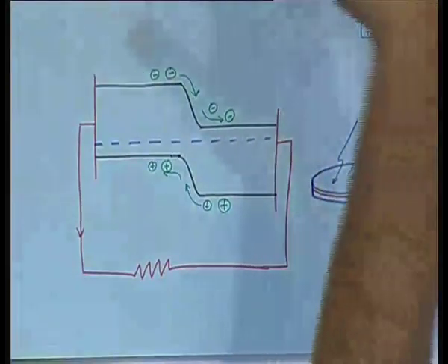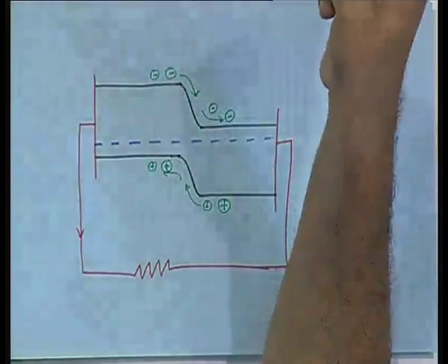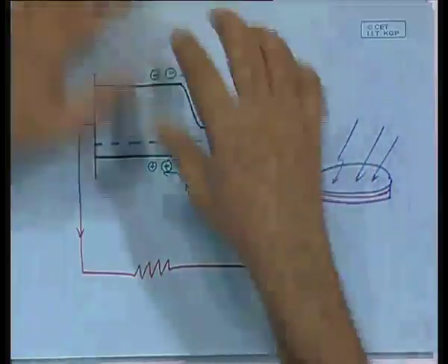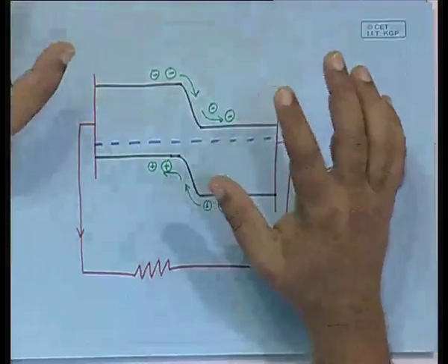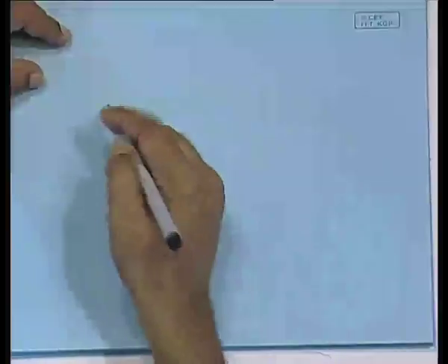So, the incident solar radiation produces a current. So, it becomes effectively a current source, not a voltage source. So, effectively you have, depending on the amount of solar radiation received, a current source. So, if you want to produce some kind of an equivalent circuit, you would say that I have got a current source.